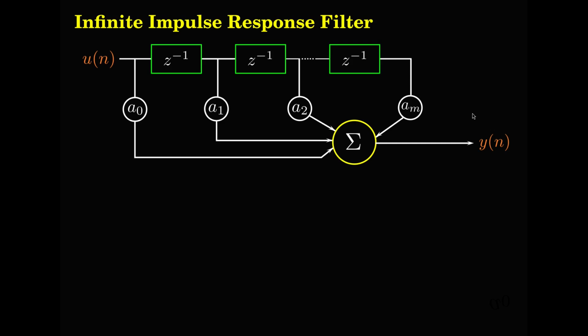Now this is the FIR filter. I'm going to add something to this FIR filter. I'm going to take a signal from output yn and delay that.